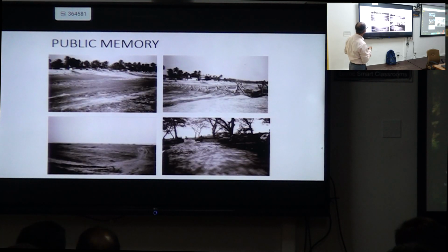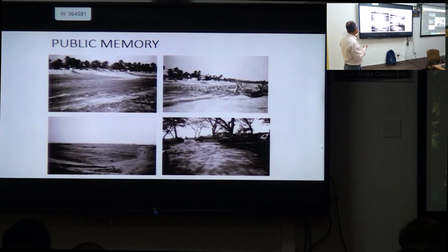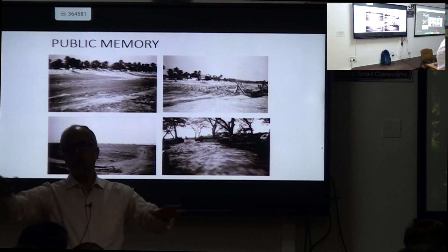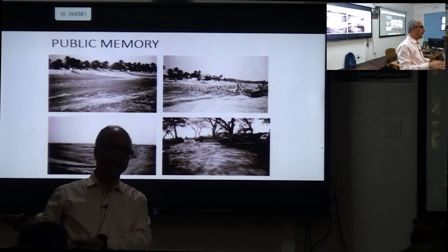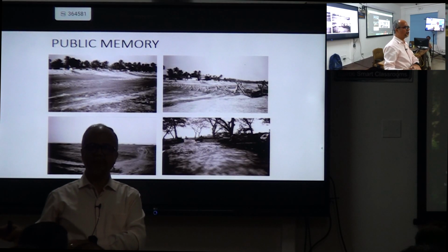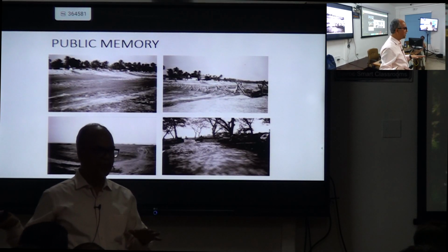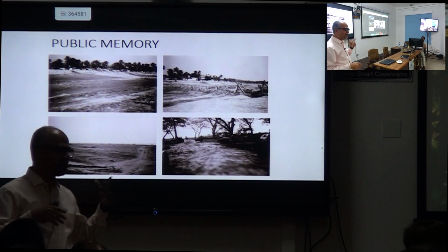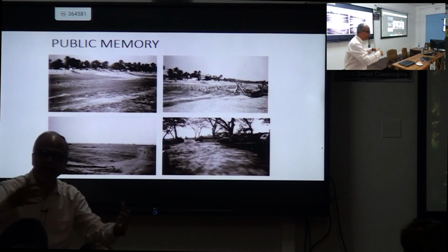We went with some submergible spar in between some porcupine screen, this kind of screen, and some submergible spar, as you can see here. So this was provided, and then our assessment was correct, and we could see that a lot of sedimentation has taken place. Immediately the next year the river went far off, and the whole portion was sedimented, and this bank is there till today. That means now it is almost more than 20 years.